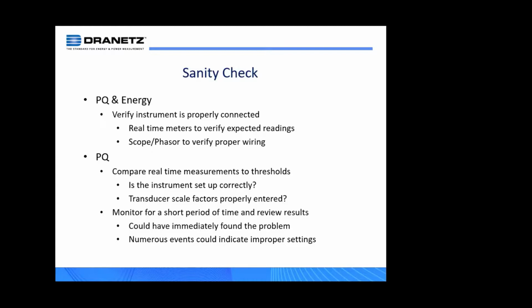And just about any instrumentation that will call themselves a power quality monitor or power quality analyzer would have the ability to detect that. But a big part of power quality is subcycle events, transient events. Some instrumentation have threshold settings to allow you to set the sensitivity of such events.